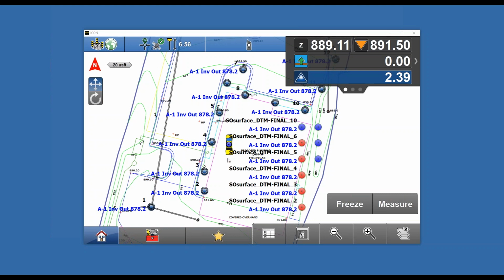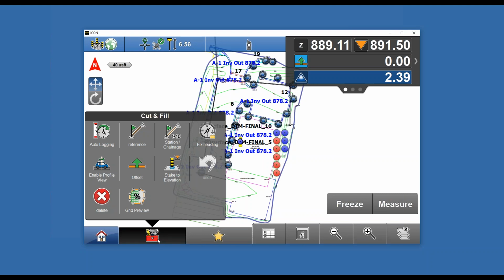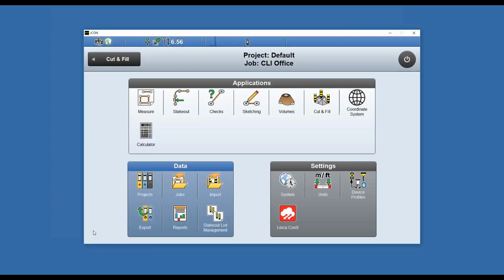And then it'll automatically update as you ride back over an area after it's been graded to show you that it's now on grade. So if it was cut before, it'll reshade it green as you re-ride it. So you can see your site develop and save those different shadings over time. That's a new feature they've just added. You also have stake elevation and enter forward profile view, so if you want to see the forward profile going up and down slopes, you can see it.